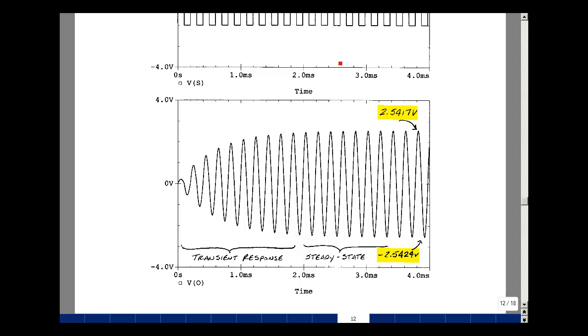sum of sine waves, and our primary, we call fundamental frequency, is 5.03 kilohertz. And that first term in our summation was 2.54, pulling that sine wave out of the sum of sine waves. The third frequency, we call the third harmonic, sees a very low gain. And so it's still there, it's just that it's very tiny when it's added into this result.